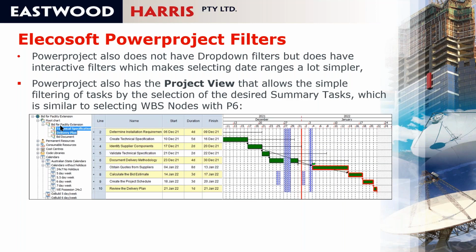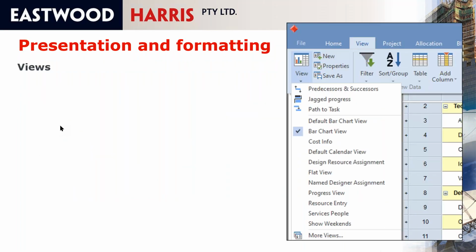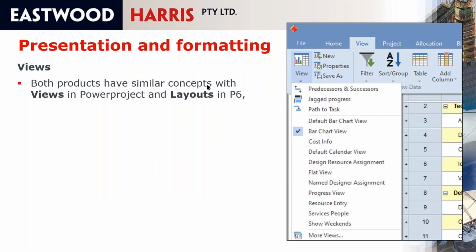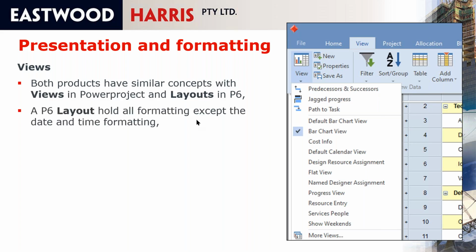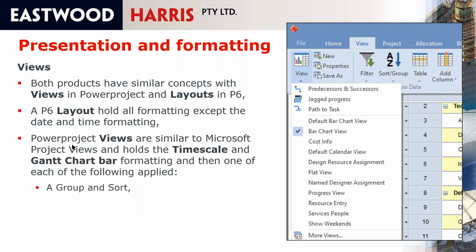Gantt chart in P6. Presentation and formatting: you'll find that both products have similar concepts, views in Powerproject and layouts in P6. Powerproject uses the same terminology as Microsoft Project. A P6 layout holds all the formatting except date and time formatting. Powerproject views are similar to Microsoft Project views, and they hold the timescale and Gantt chart, and then you apply a group and sort, a table, and a filter.